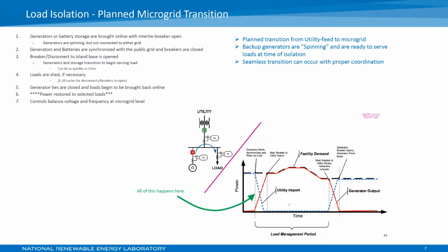So what happens up in the top left, steps 1 through 7, it states that you bring all of your microgrid generation online and get ready to serve all of your own loads. Just like that graphic up top in the last slide, you synchronize your generation storage with the electric grid's generation. Then you try to make it so that your generation is meeting your own load, and then there's no power going in or out to the utility. And then once you have zero power going across that line to your utility, then you would open that switch and you're now operating as an isolated grid. And all of that can be done manually or automated, and I'll get into that a little bit later when we start talking about smart grid in that space.